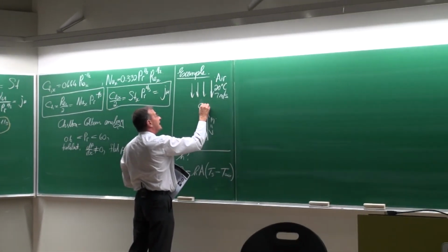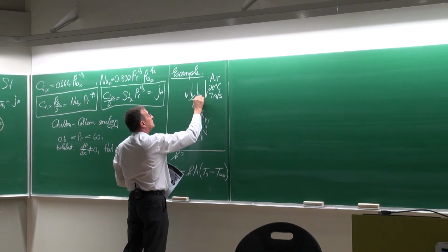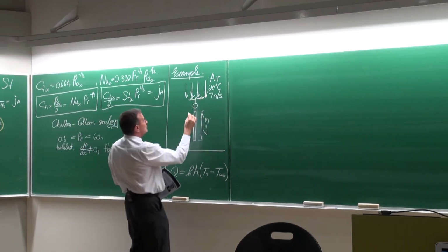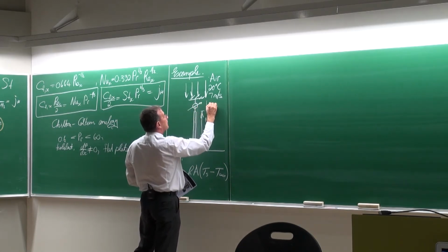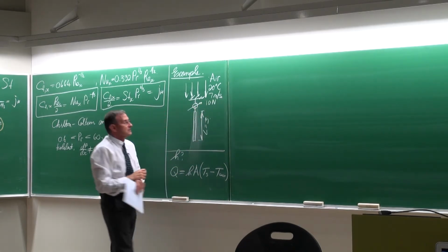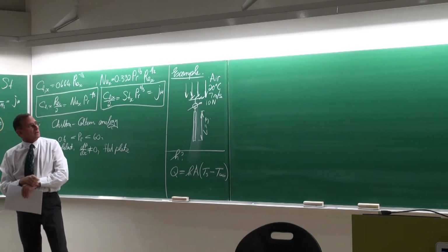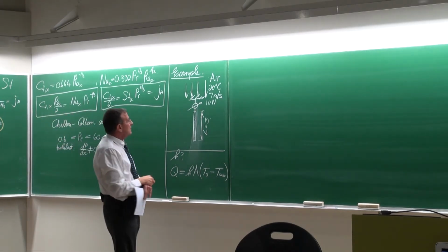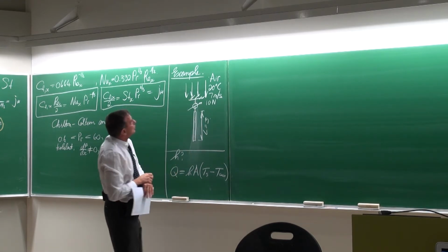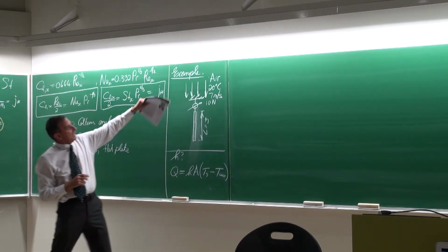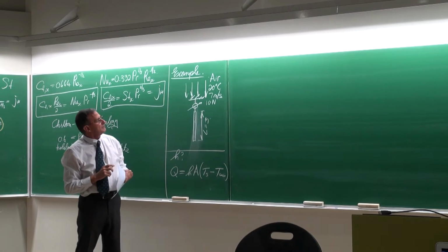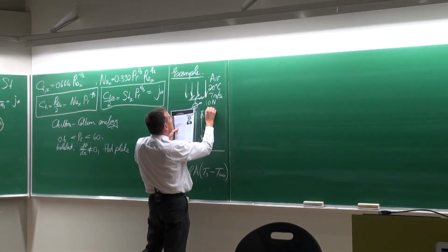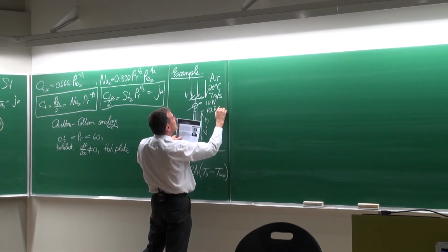You put a scale there and you hang the plate up. And on the scale, most probably, let's suppose the force would be 10 newtons. The mass multiplied by the gravity. Okay, that is then before you put on the fan that gives a velocity of 7 meters per second, and after you've put it on, it is going to be 10.86 newtons.